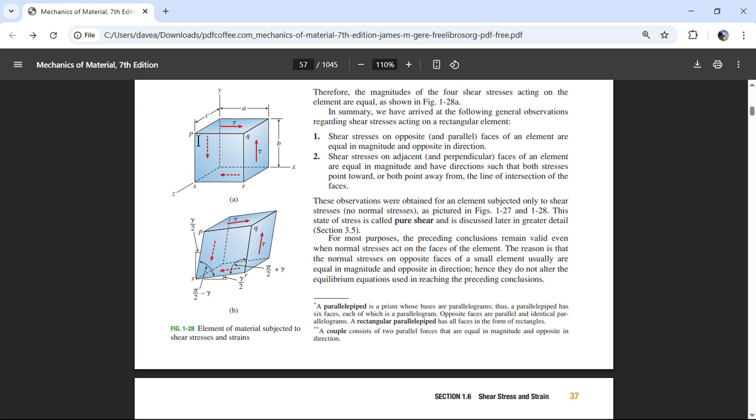All right, so this area is going to be square root 2 times that area. And that means that whatever force this is, it's going to operate over a bigger area. So you can find the normal stress, the normal pressure, as this normal force divided by that area, which is square root 2 times the original area. All right, and that's just one element.